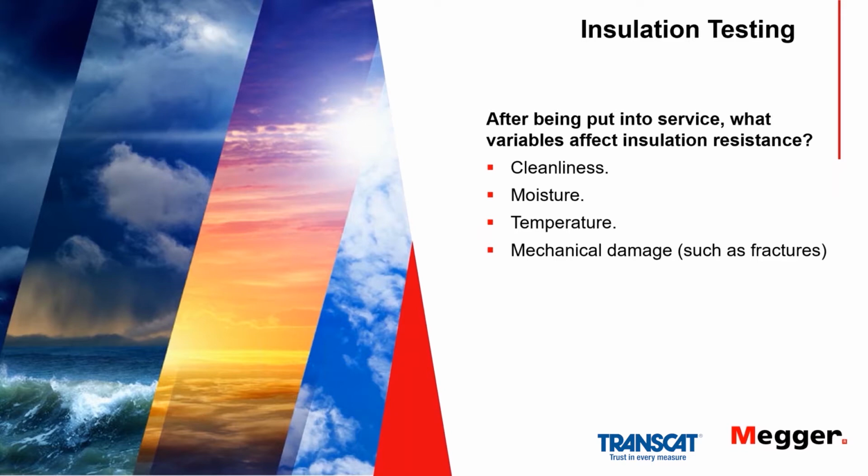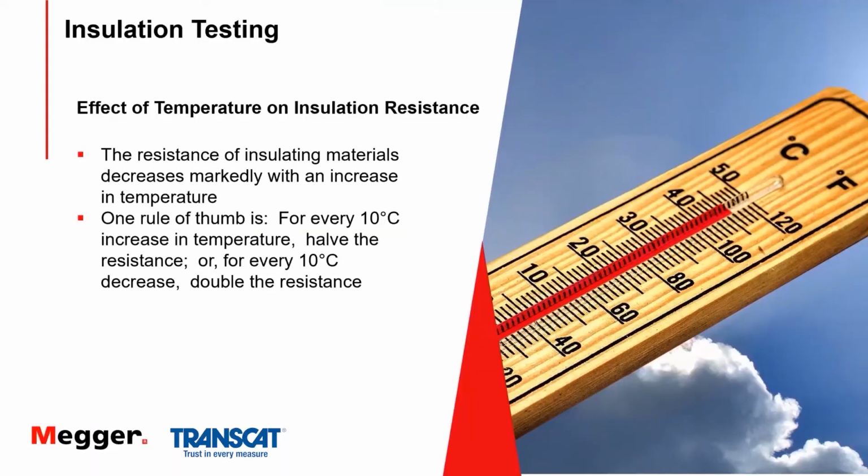And so cleanliness, moisture and temperature, and mechanical damage are all parameters that are kind of ongoing effects on your equipment and can be reflected in your insulation resistance readings and give you an evaluation of the condition of the equipment. Okay, temperature.